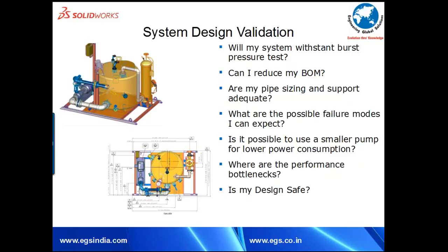When we investigated this problem using simulation, we looked at the cavitation, we looked at the blade bypass frequency, and we said it is because of the clearance between the impeller and the housing leading to a cavitation loss, and leading to a loss upfront and downstream because of the pipe bends. A combination of this was pushing the critical speeds towards the operating speed, leading to vibrations. Whose problem is it? It is a joint effort which has to be taken by the pump supplier along with the petrochemical industry major.